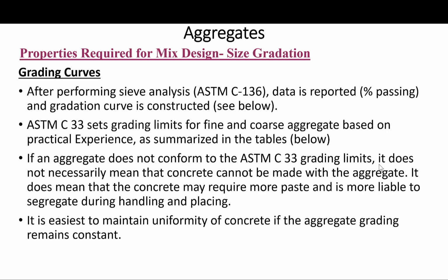These numbers can be plotted graphically against the sieve size, as I will show again on the figure, to give us the grading curve. It is customary to use cumulative percentage passing on the ordinate. The successive standard sieve sizes are plotted linearly on the abscissa,